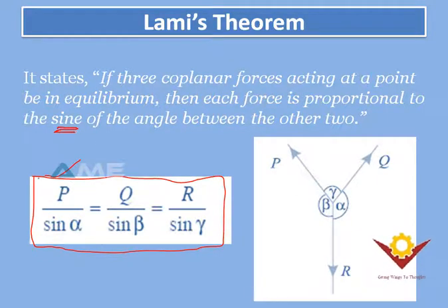We can also call Lami's theorem the sine rule, which is there in your trigonometry or some other primary educations. And once again, Lami's theorem you are going to use for forces which are acting coplanar and concurrent, and here the forces should be three which are in equilibrium.